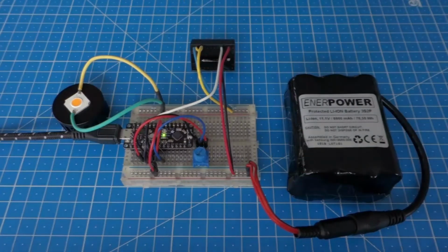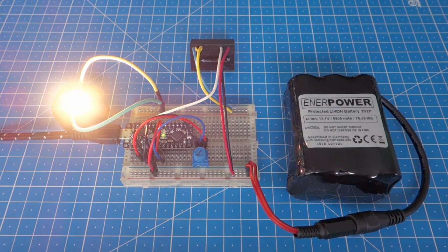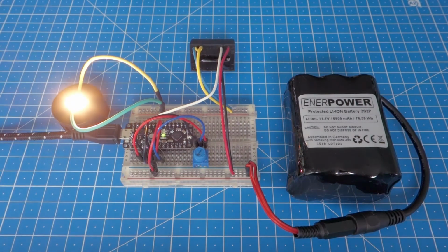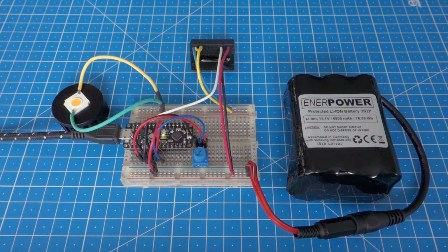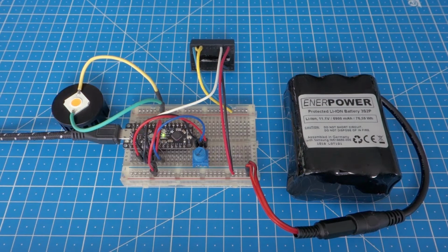To get around both problems, we use built-in timer 1 with 12-bit output, and instead of slow calculations in code, we use a pre-computed lookup table with exponential PWM duty cycle values. Another benefit is dimming with a frequency of 4 kHz, which means that there is no perceptible flicker. Look at the code with detailed explanations for how this is done.